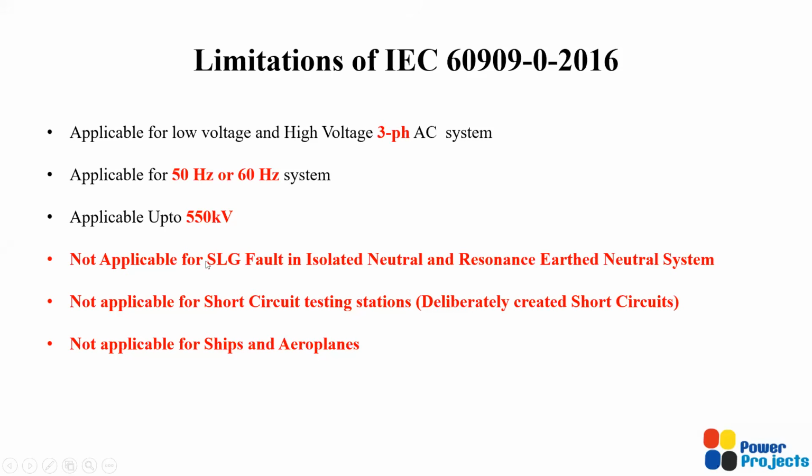If there is any single line to ground fault in an ungrounded system, which is an isolated neutral, or in resonance earth systems, which are also called Peterson coil or compensated earthing systems, this standard is not really applicable. And the standard is also not applicable for deliberately created short circuits.